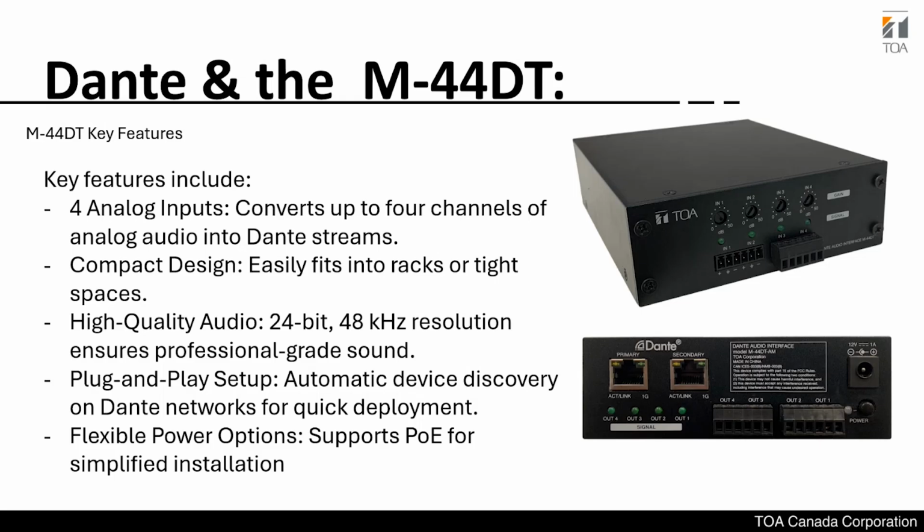It's very easy to use in a rack. It has high quality audio, the Dante standard of 24-bit 48 kilohertz resolution. It's perfect if you have any location with a Dante setup, and it's plug and play. This is another good thing with this device. It is automatically discovered by the software, so we don't have to look into IP addresses and all those things. Also it's very easy to use because it works on a PoE switch, so you don't have to give any additional power supply to this device. This is the key point for this product.